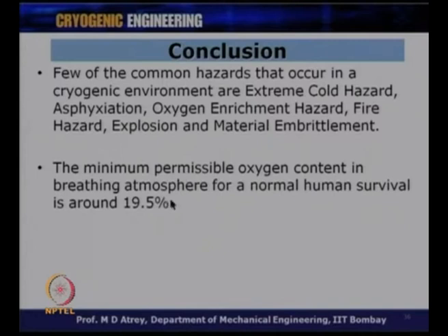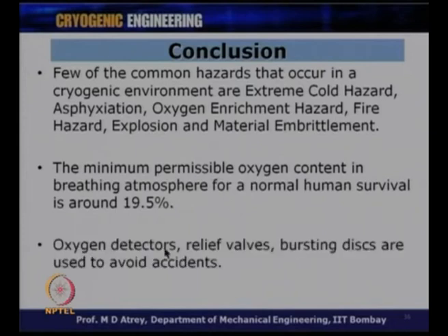It will lead to unconsciousness, choking, breathing problems, and it can lead to sudden death also. Oxygen detectors, relief valves and bursting discs are used to avoid accidents. These are very important devices that should be kept in your laboratory, and relief valves and bursting discs are design aspects that should be ensured while designing cryo containers or big dewars.